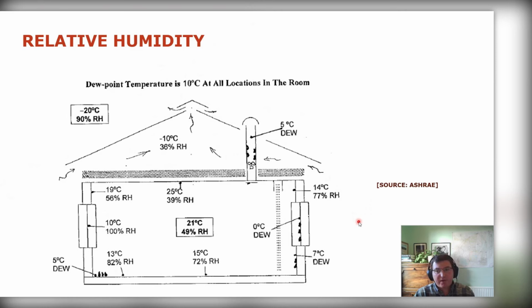On the other hand, if the relative humidity is high, close to 100, then it means that it cannot pick up that much moisture, so it's not going to be very good at drying, but also there's a risk of condensation, and also things will generally feel quite heavy and mucky because of that.